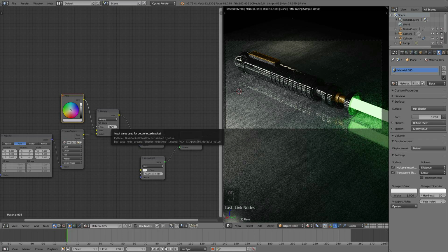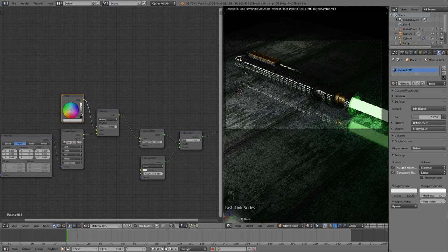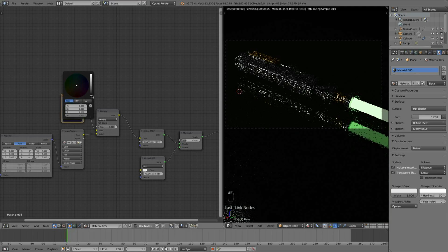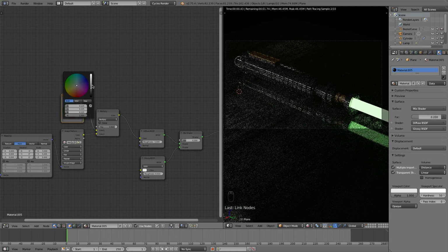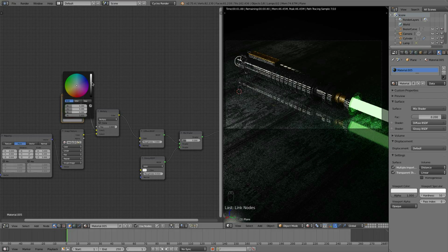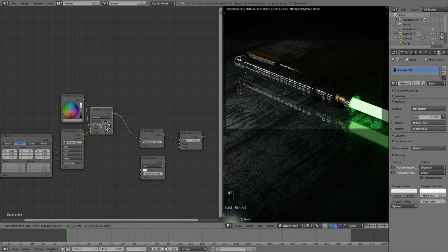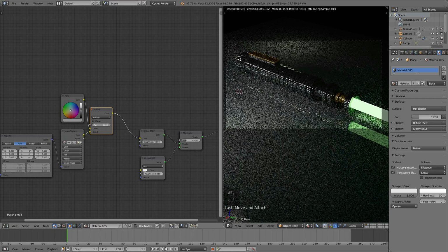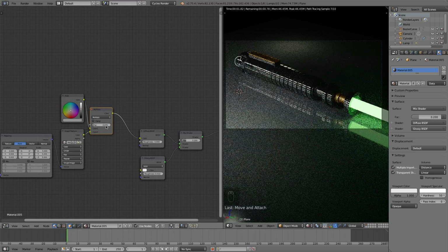And I don't want it to be so visible. So I'm going to make it just barely in there. Go about 0.9 and then make this much darker. Whoops, not quite so dark. Something like that. Alright, now I'll take that way down, the opposite direction, about a 0.1. Just want a little bit of that grunge coming in on the floor. That's kind of working, kind of not enough, maybe. Maybe go 0.15, 0.16, something like that.